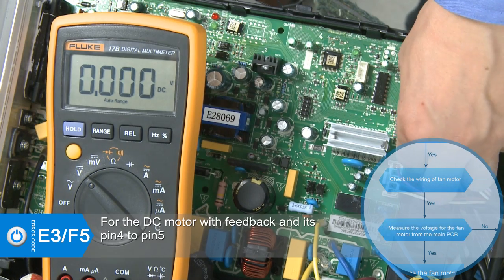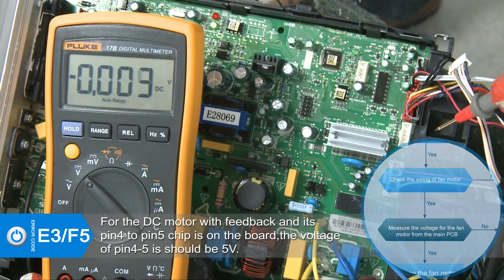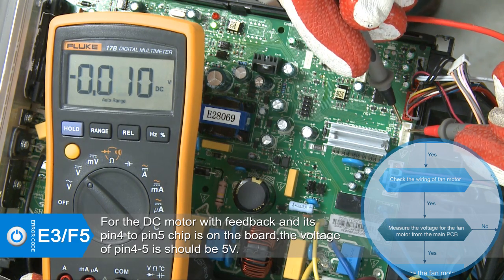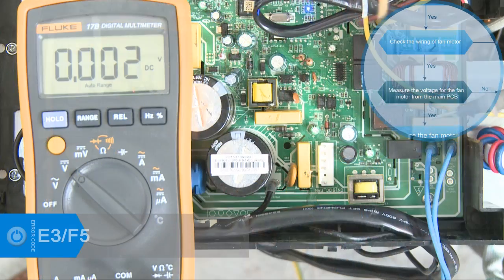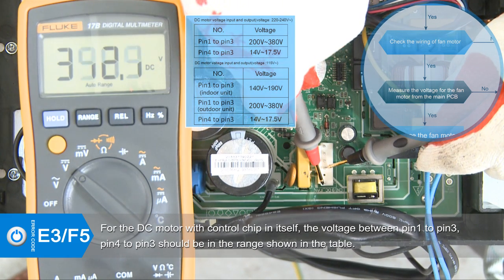Examination for main PCB board: DC motor with feedback and its control chip is on the board. Turn the power on. When the unit is in standby mode, measure the voltage of pin 4 to 5 in the feedback signal connector.